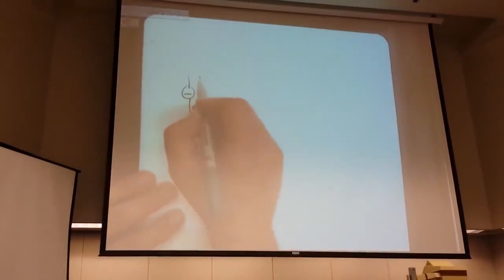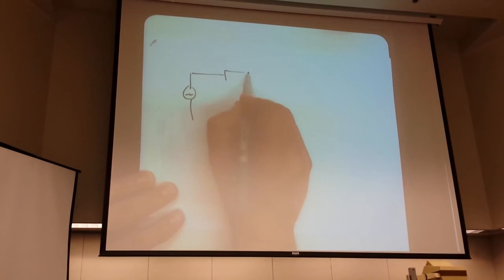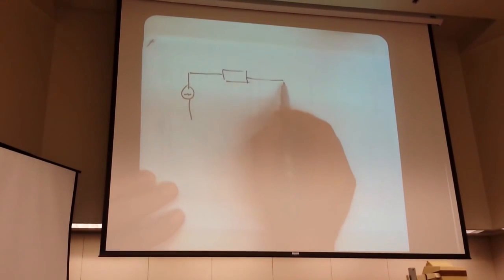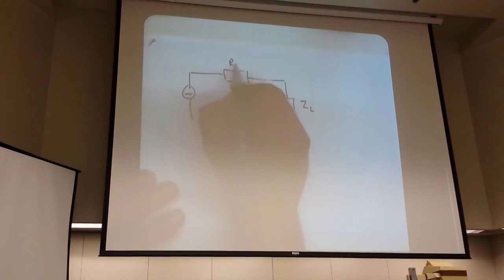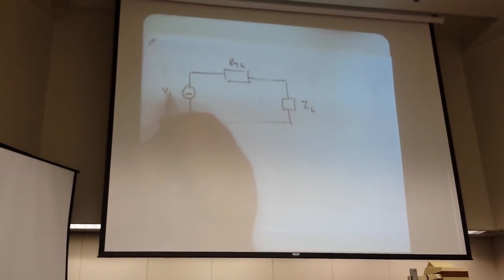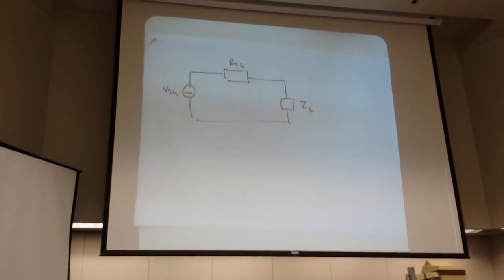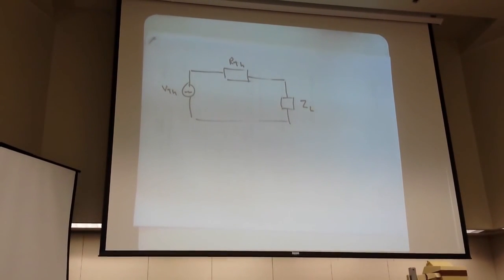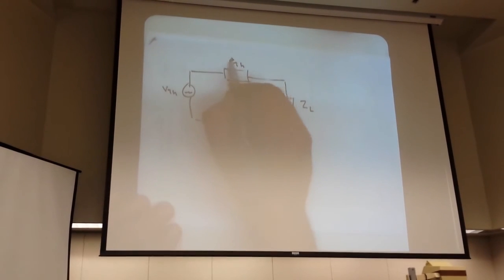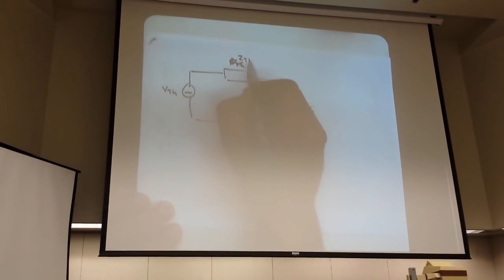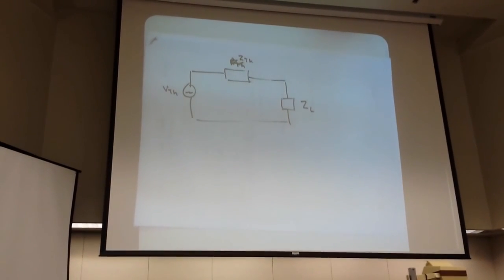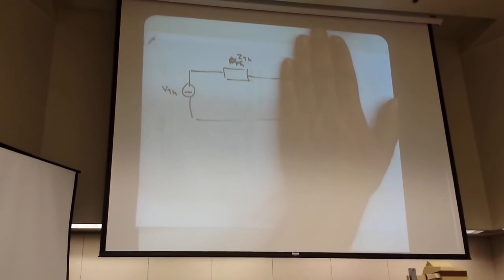Thanks. So no matter what our system is, if we consider this R Thevenin and V Thevenin, which we always can, let's call it Z Thevenin. We can always ultimately get our circuit in this form. Remember, off to the left, we can have all sorts of stuff.